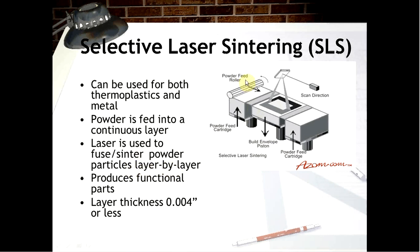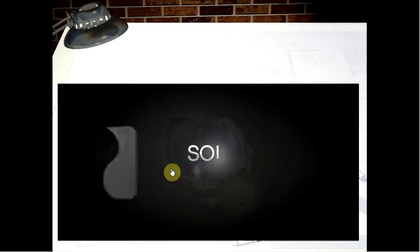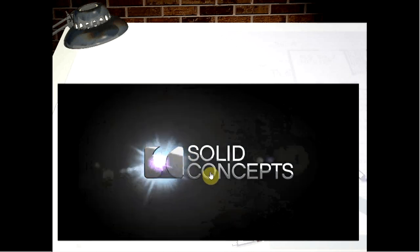First, when powder is fed with the help of the powder feed roller, then the laser is bombarded and the pattern will be generated, and after that pattern, the build envelope piston will get down to some extent, and then once again powder is fed by the roller onto that metal, and once again the pattern will be generated in such a way that the whole 3D model will be generated after some time. This is layer by layer additive 3D printing. Okay, this is the video, you are able to see it. This is generated by Solid Concepts.